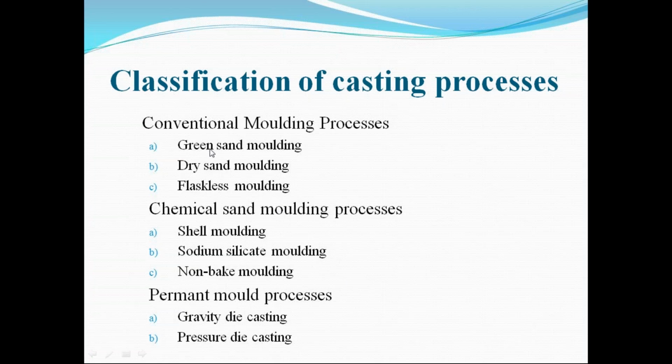Now I discussed the sand mold casting process. There the main problem is that for making each and every product, it's required to prepare the mold, and after solidification of the liquid material, it's required to break the mold to get the product. That means for each product a separate mold is required, and after solidification the mold must be broken. So the mold is no more permanent. It requires huge time and huge investment. That problem we can solve by using the permanent molding process.